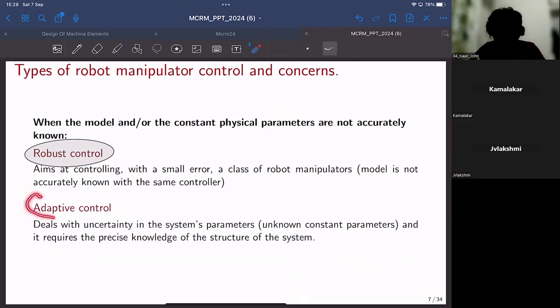In the case of an adaptive controller, we use it where estimation of the model parameters is no longer possible, because they vary as a function of time. For example, an airplane's mass changes through its journey due to the burning of fuel.